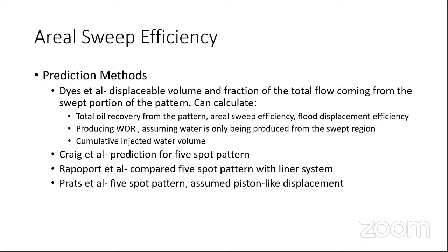So for prediction methods for areal sweep efficiency, you have Dyes et al., which is a displaceable volume and fraction of the total flow coming from the swept portion of the pattern. That can calculate the total oil recovery from the pattern, areal sweep efficiency, and flood displacement efficiency. You have producing water-oil ratio, assuming water is only being produced from the swept region. You have cumulative injected water volume.